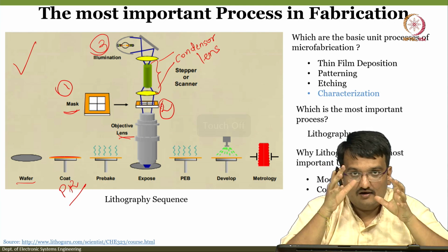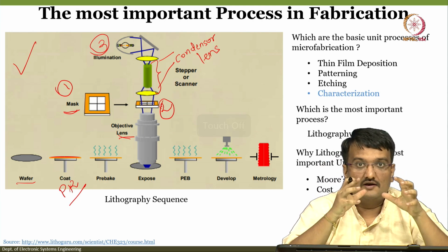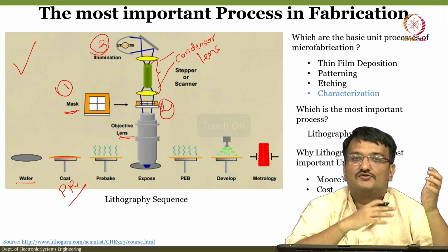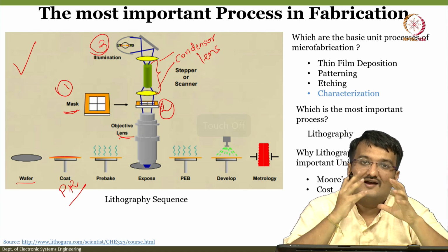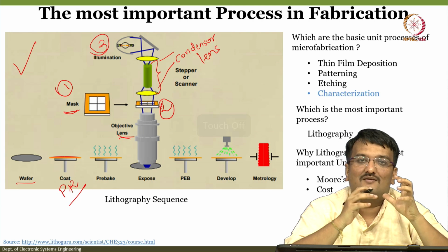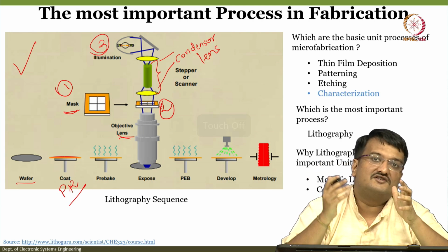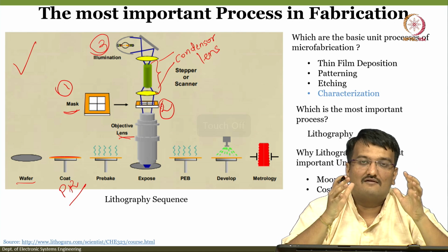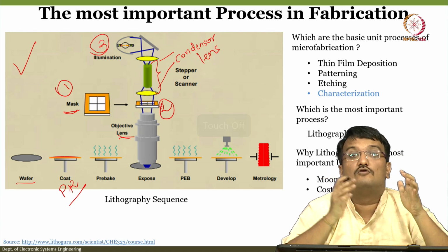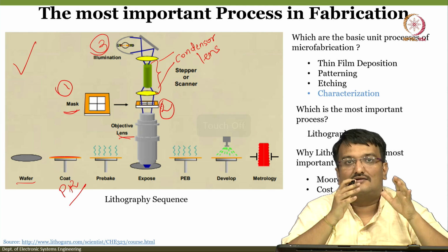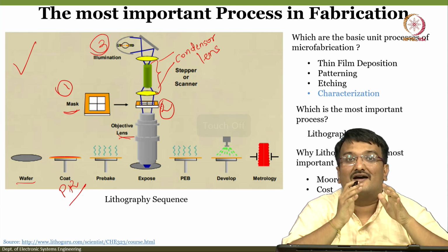Ultimately the entire lithography game is about how light travels from the illumination source to your wafer, how you can control that, and how precisely you can manage the beams of light and their energy. That is the entire ball game when it comes to lithography, and that's why it's called photolithography. A very important point: beneath that, the main principle is diffraction.